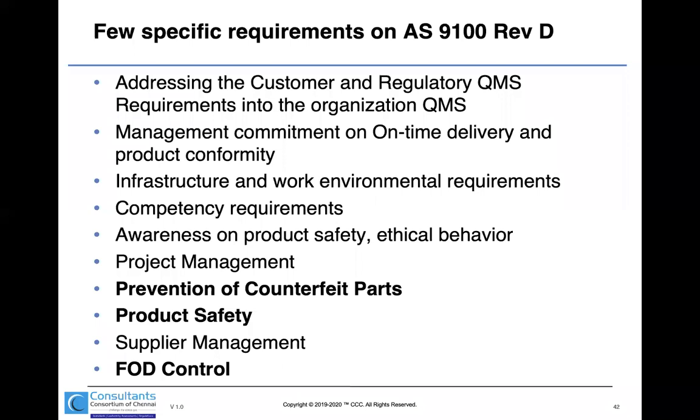We might have done some outsourcing activity, right? For that particular part, maybe welding or some heat treatment. How are we going to ensure the supplier who did this welding and heat treatment is also keeping this record retained for 35 years? So you ask them to keep it, or you retain those documents on your end. Those types of clarity we have to address in our own QMS.